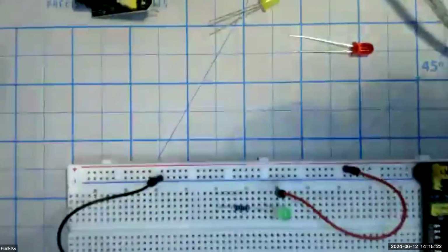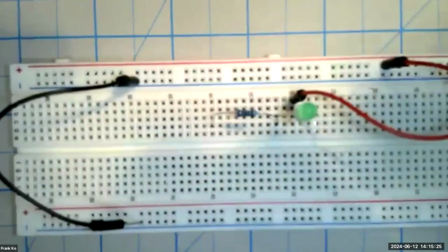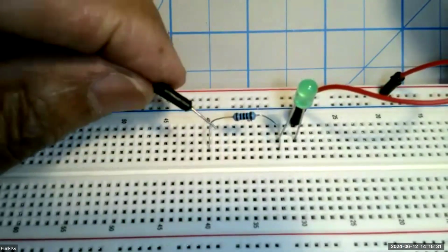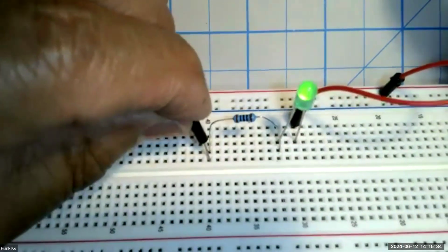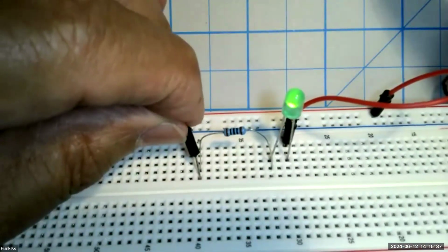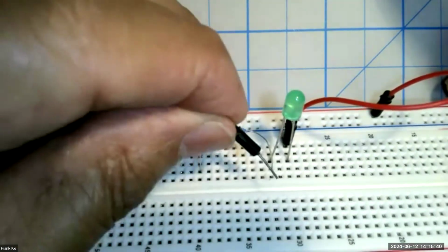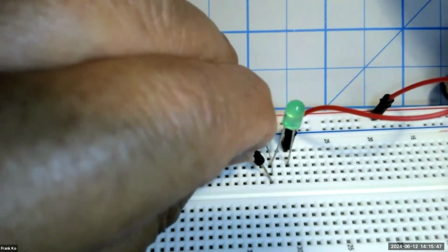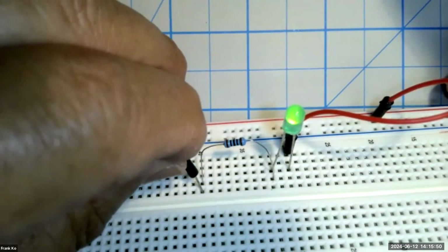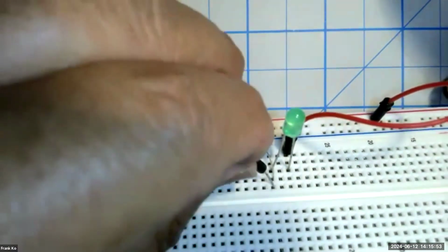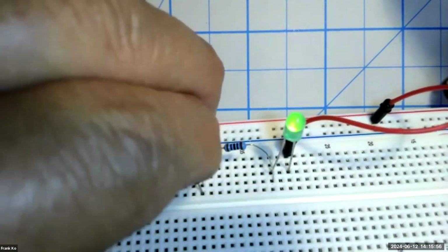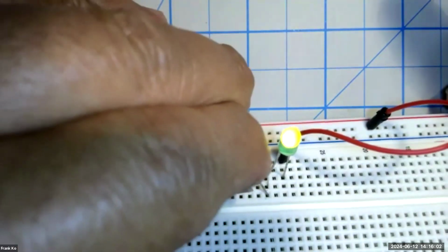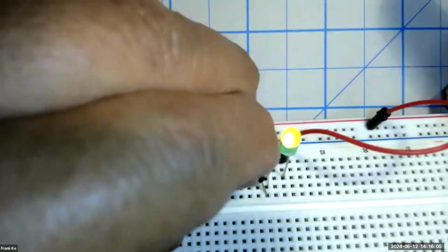And for those of you who want an even better view, let me just bring this right down. With the resistor, I'm connecting the black jumper wire to the end of the resistor, so it's now in series. You can see I've got that amount of illumination. If I bypass the resistor and come straight up to the LED pin right here, boom, quite a bit brighter. So the job of the resistor is demonstrated by it limiting the amount of current that flows through that LED to protect it. We still have enough illumination from the LED to show that, yeah, it's on, circuit's working. We don't need the LED super bright as here because we can burn out the LED.